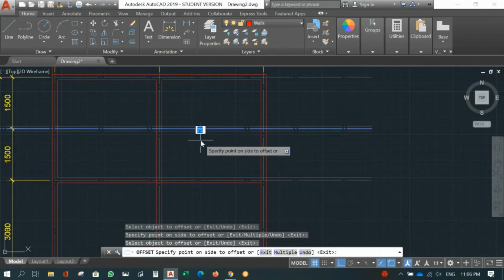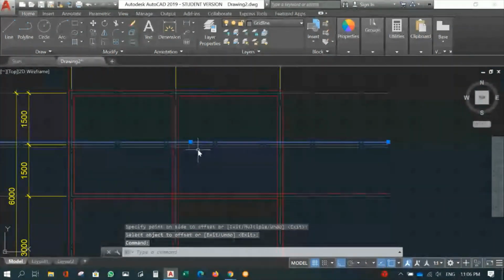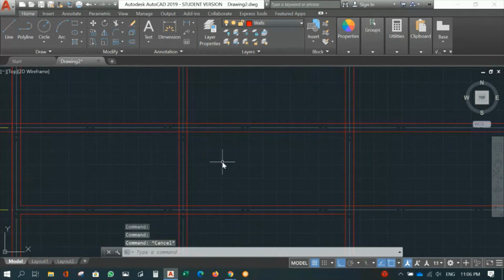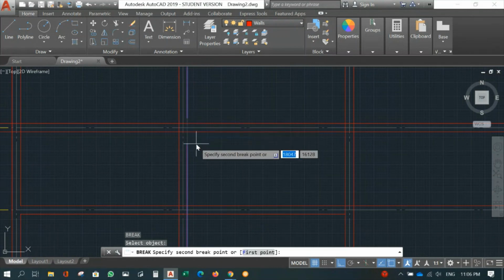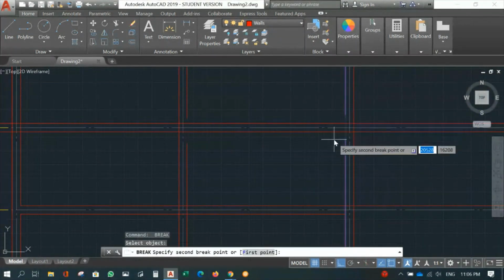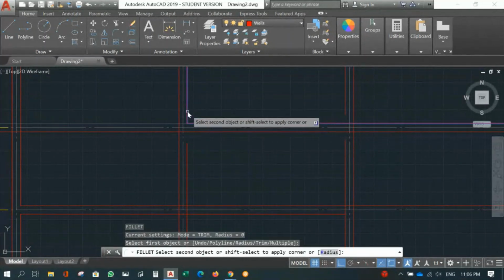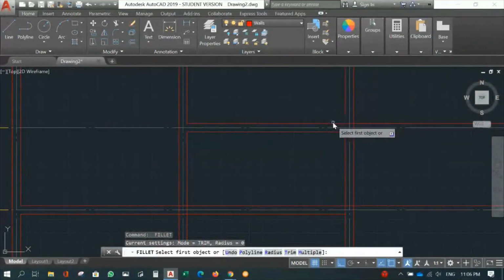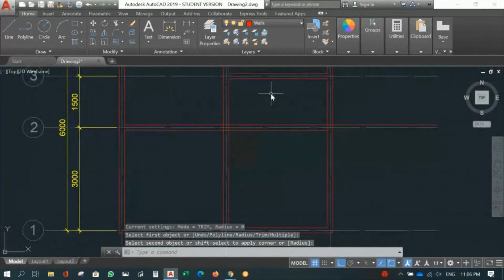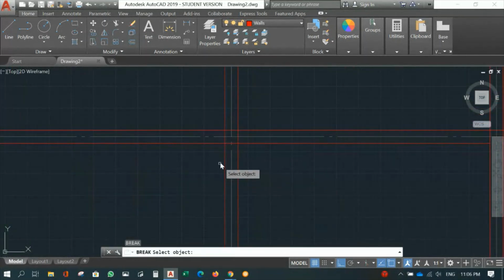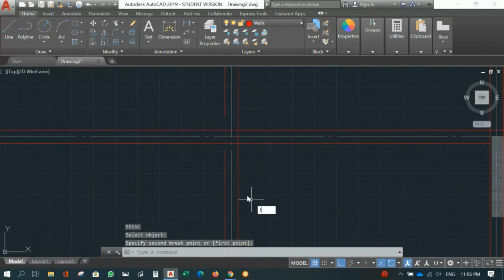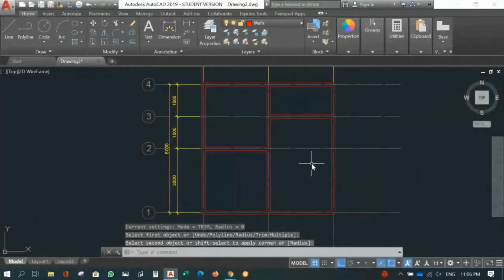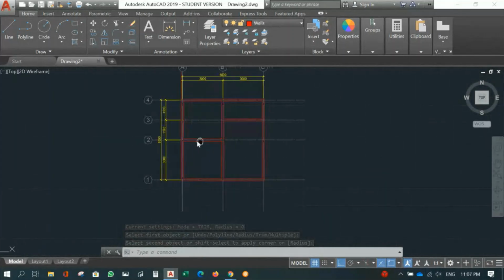Right. So the last one here is the toilet, 75. Okay, so change the layer into walls, right? And then break this in the arm. Repeat the same command, just space bar, and it will give you the last command. Same thing here, BR, then fillet. Space bar to repeat the last command and fillet. And that's it. So we have created a wall.